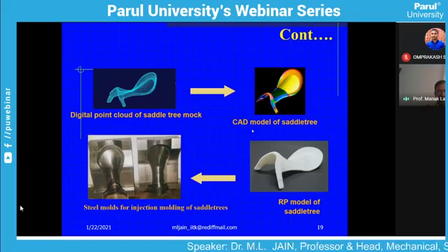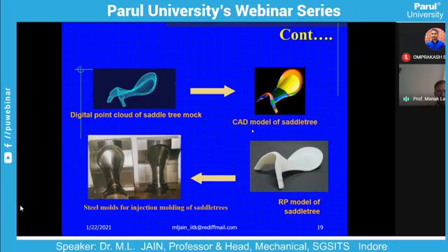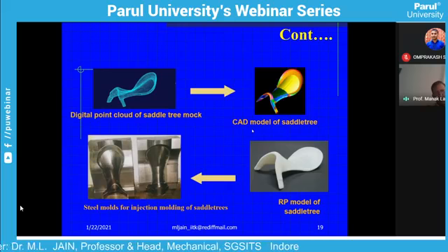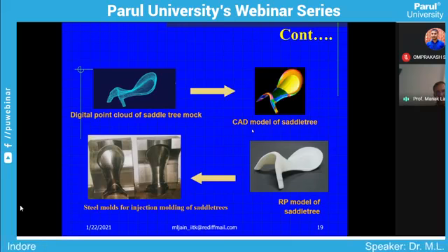On left top, we are having a digital copies. Then on top right, we are having its features, different defined features, surface solid models, and then you are having its prototype, that is RP models, rapid prototype parts, and then this rapid prototype model is used for generating the die for multiple 10,000 pieces or 20,000 pieces in injection molding machines.